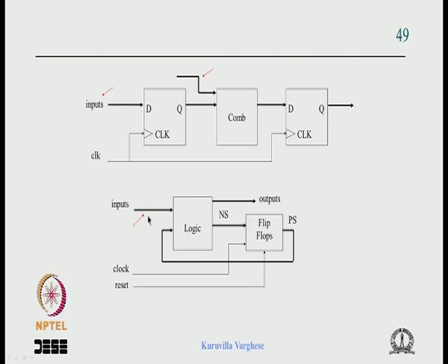It does not matter because it is coming randomly; this logic will not do any good. If it is quite random with respect to the clock, this logic delay makes no difference, because the whole pattern is shifted by a constant delay. As far as the probabilities are concerned, it does not change the probability of a setup or hold time violation, because a constant delay will not do any good.